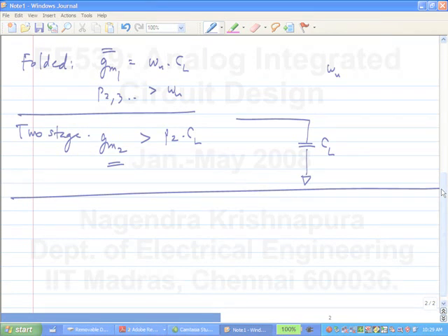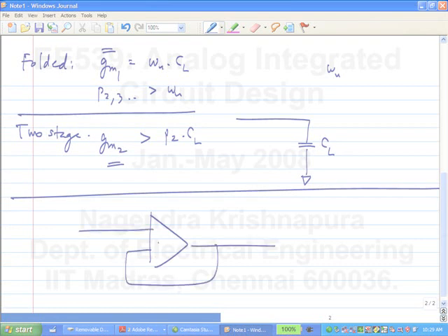So you are interested in the output resistance in feedback, right? The output resistance in feedback is a lot lower than the open loop output resistance. So that's how you get the low output resistance. Now of course, if you put a two-stage op-amp in feedback, you will get lower output resistance than if you put a folded cascode or a telescopic cascode in feedback. But still, you shouldn't look at the open loop output resistance. It's the closed loop output resistance that matters.